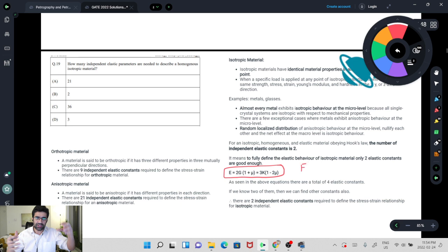So out of these, E equals 3K(1 minus 2 mu). You see, out of these 3, if you know 2, you can calculate the third one. Now in case of anisotropic materials, you start to have these moduli in matrix form, so it gets slightly more complicated over there.